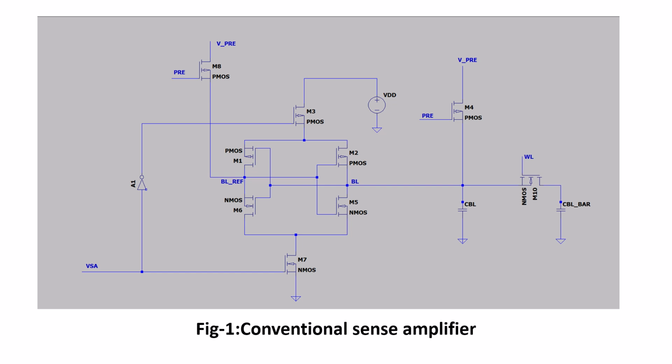So this node voltage is directly connected to this ground such that the discharging of this node voltage is faster than the discharging of this bitline node voltage. As a result of which, as this is discharging to the ground, there is a chance of turning on this PMOS. So at some point of time potentially this PMOS is going to be turned on and this VDD appears